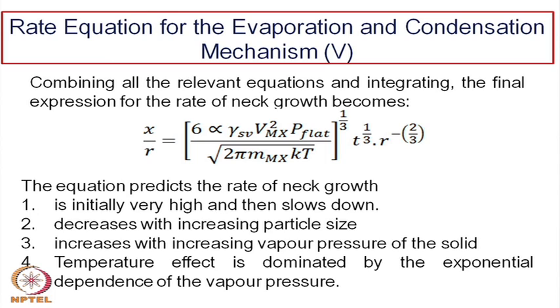So, it is not only the temperature; the temperature effect of course will come later, just now in a minute. It is time, of course, which is anyway the rate determining factor. The larger the time, the more the densification will be. Of course, in this particular case there is no densification, but the sintering will take place, the neck growth will take place. Okay. So, even if there is a neck growth, there is no densification, that we have seen earlier. So, both time and the initial particle size are the two most important parameters which actually determine the sintering process.